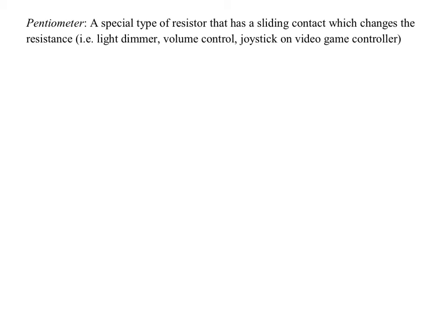Two things, both theoretical. First, when I shut off the switch, the light just turns off. But if I wanted to dim the light, what I'd use is called a potentiometer. And a potentiometer is a way to make a variable resistor. So it uses metal contacts between the two different pieces. So for example, you take the light switch and you rotate it to turn it off, or you lower it down. You're changing the amount of metal that's in contact, and as a result, you're changing the resistance of the element, and therefore the brightness also changes. Okay, the brightness of that bulb changes when the resistance itself changes.